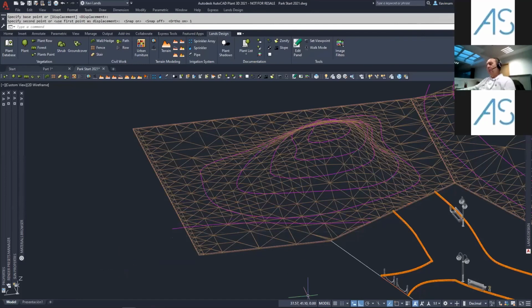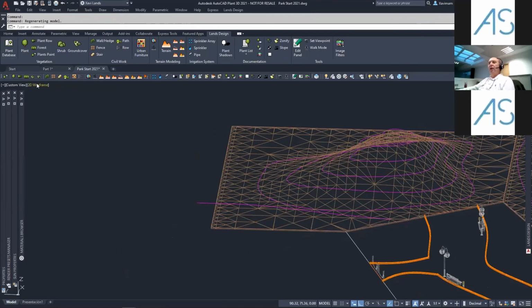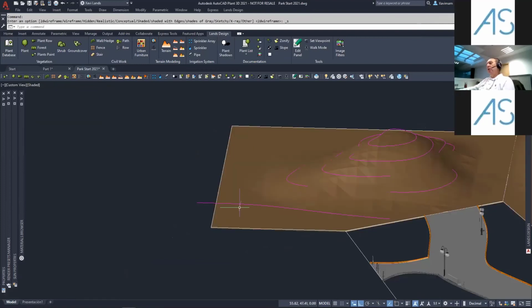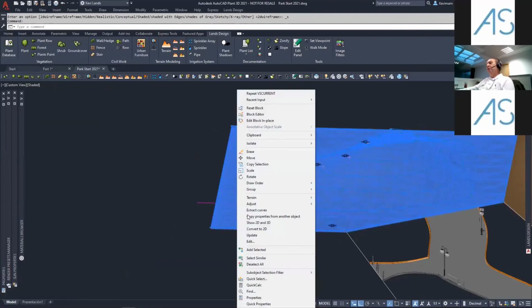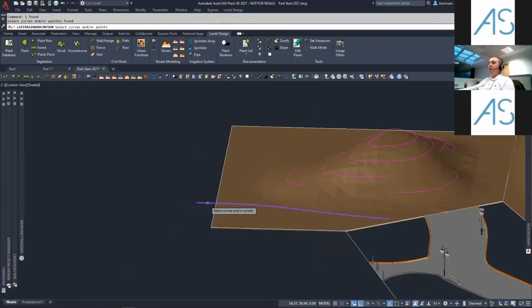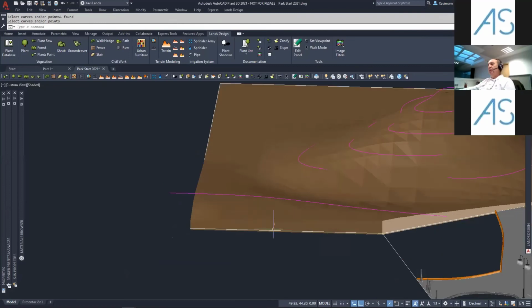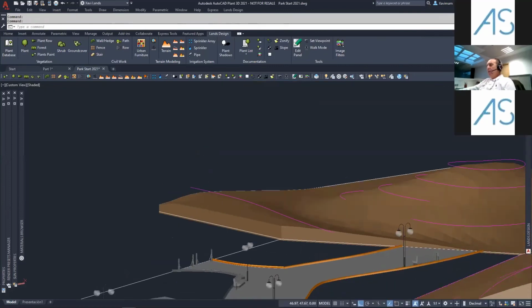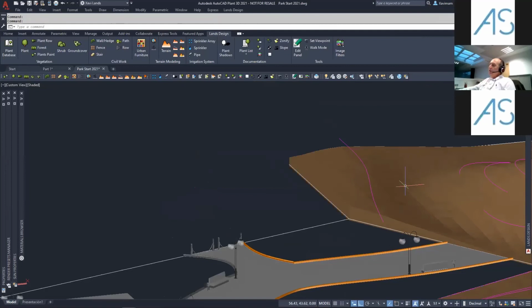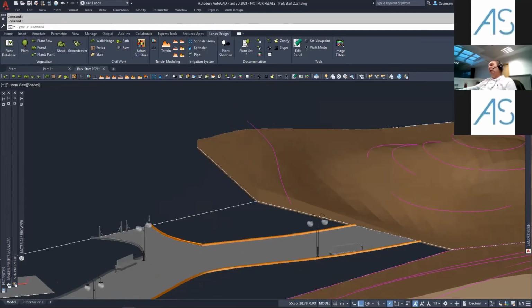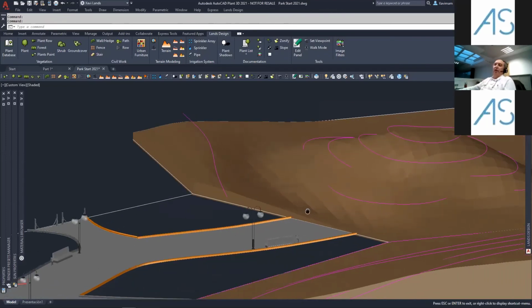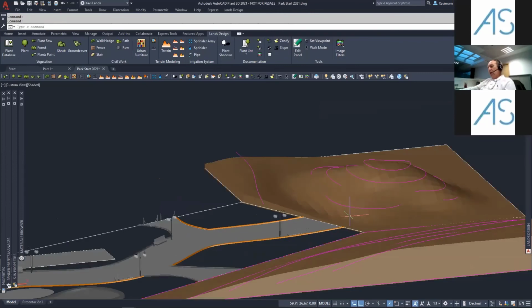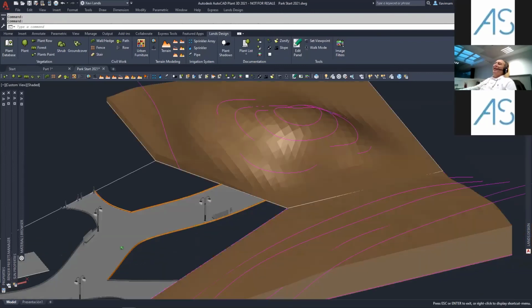and then I'm going to move 3 feet, in my case 1 meter. I'm going to place this in a shade mode so that you will see better. Then we have the option to select the object, go to terrain, add a contour curve, and select this contour curve here. And as we can see, the terrain has been modified, creating this canal here, driving my rainwater from the hill, and of course from this side as well, to an area that I am interested in, because there is a water collector or whatever.